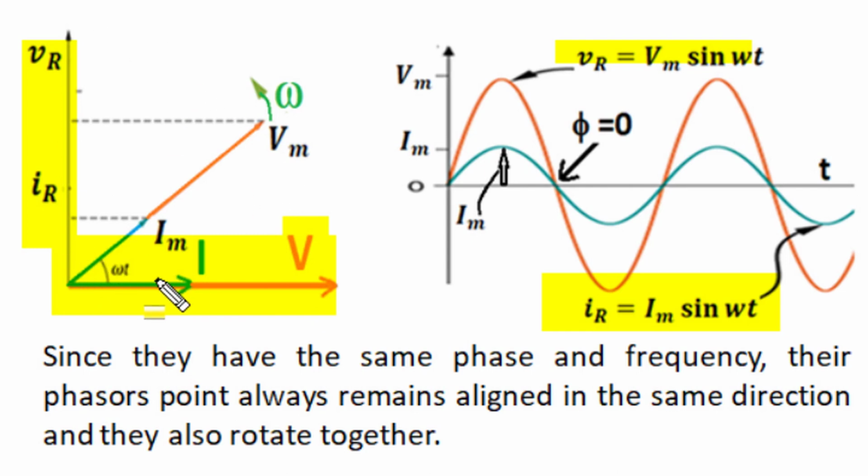So these rotating phasors always remain in phase with each other during their rotation, and in frozen state when rotation is ceased, the relative position of voltage and current in the same alignment would be the phasor diagram for pure resistance, voltage and current.